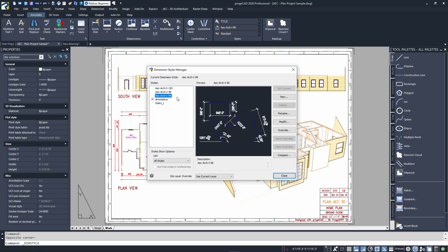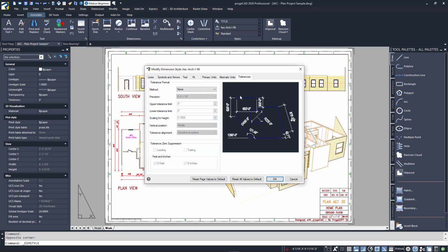Why is this done? To match the text and dimension elements when viewed at scale on a 1-to-1 drawing, a piece of 3/16 inch text must be drawn 96 times larger than 3/16, which becomes 18 inches tall in model space, but viewed at 3/16 on the plot. This same scaling and style naming concept is often used with text and annotation as well.